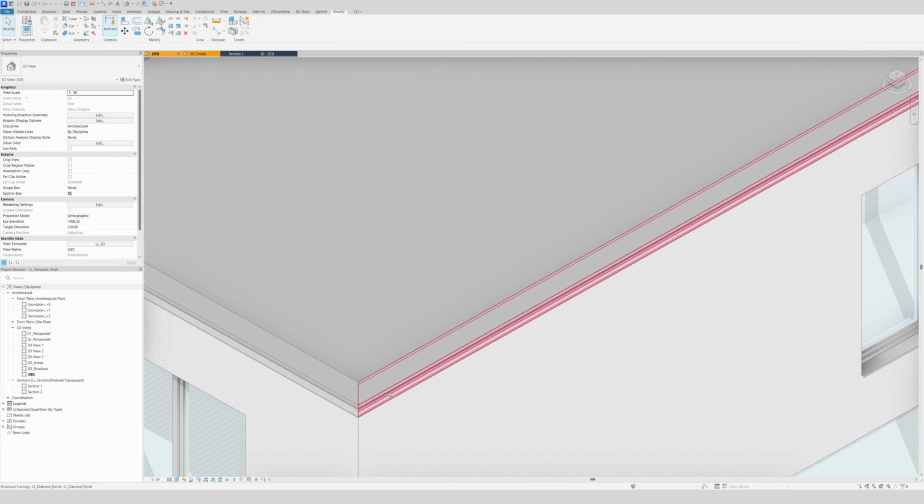So first things first, we go to File right here. Then of course we go to New, and then we select Family, and then we'll look for structural framing right here, beams and braces. Click it, open it, and voila, that's what we have. I'm gonna open a 3D, and I will set this 3D right here. Voila, do ZA. So we have the model centered.